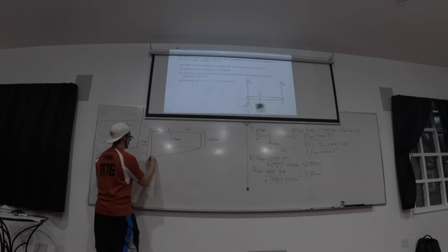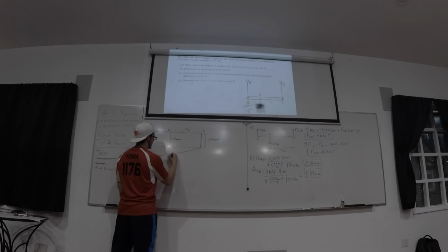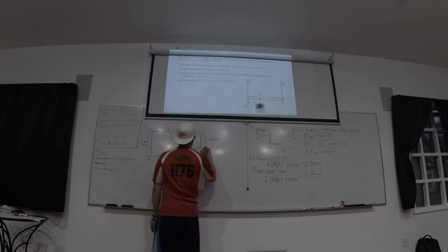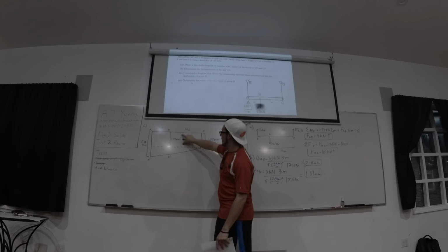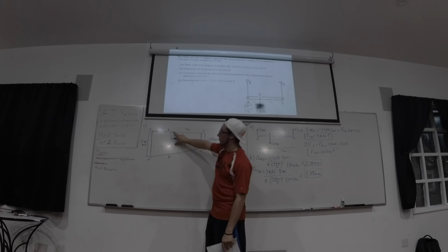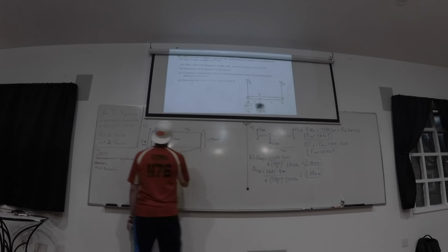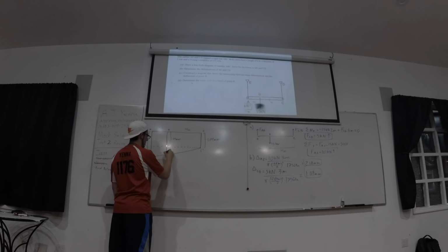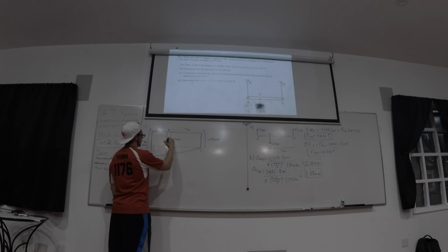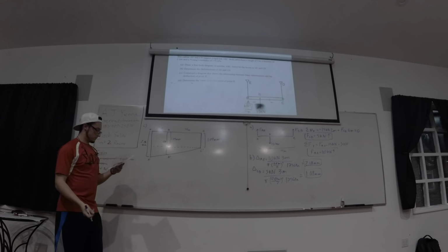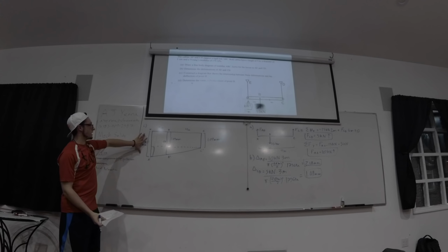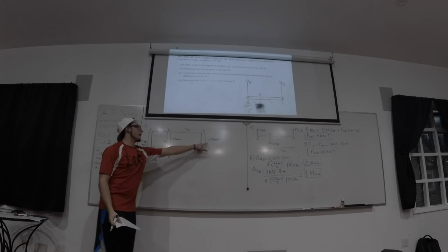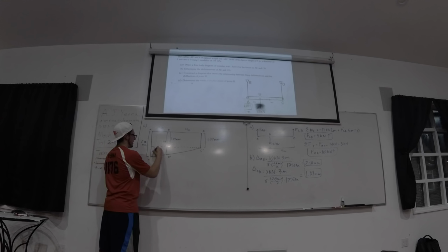Just for sanity, down here we'll call this A prime, that's the new point, B prime, C prime. This guy moved down more than 1.09 millimeters, but we know this length to start. So the actual displacement of B is this. We also know this distance here because it is 2.18 minus 1.09, which comes out to 1.09.